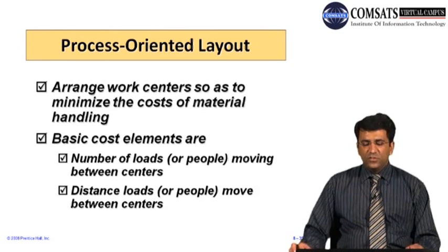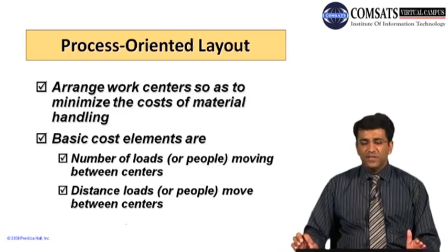Process oriented layouts should be targeted to arrange the work centers so as to minimize the cost of material handling, and the basic cost elements in this particular case are the number of loads or people moving between centers, and distance loads or people move between the centers. Now this is very important, that we will have to have an estimate that what are the different number of loads, that is the number of peoples which are to be moved between the different centers in that process oriented layout.